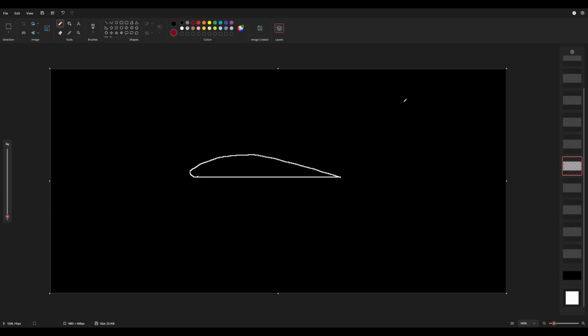Alrighty, so the last two terms we're going to talk about today are something called relative wind and angle of attack. So, relative wind is a term we use to describe the flow of air as it impacts an airfoil. Relative wind is something that's always going to be parallel and opposite the direction that the airfoil is traveling, otherwise known as the flight path.